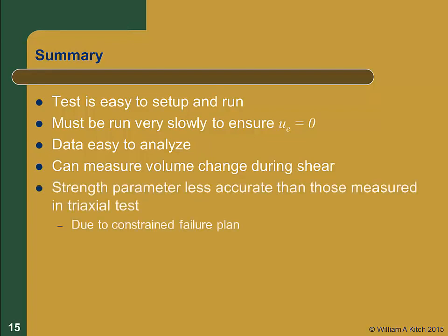The shear strength parameters measured in this test are less accurate than those measured in triaxial tests. This is mostly due to the fact that we constrain the soil to fail on a certain plane rather than letting the soil fail on whatever plane it would like to.